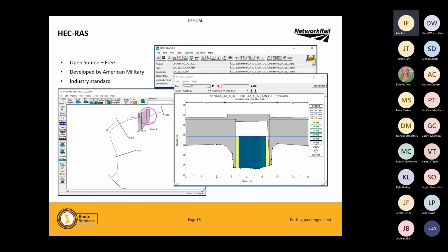It is going to be a quick look at HEC-RAS. There it is. That's it. No, I'm kidding. So it's a very basic program, but it's very clever with the programming back end. So the blue line is the water course. The green lines are the topo surveys where they've done some cross sections for us. The red dots that you can possibly see are where the modeler has said that is the top of bank. So normally the water would be contained within those two red dots, and the extension of the green line is a floodplain. So it shows it on this quite nicely.